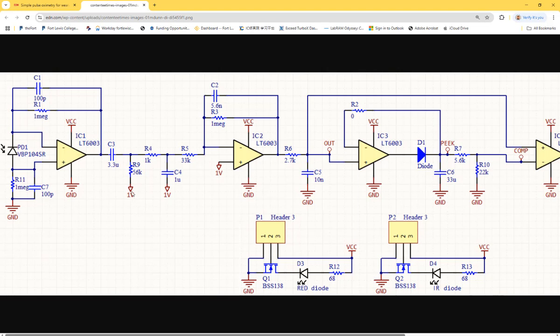But usually we use 50% of the VCC as the default DC offset. We always want your signal to swing around 50% of the range. Here's your top power rail, here's the ground, so it's basically half of VCC or VDD in the middle. So maybe 1 volt is 50%. If it's a 3-point-something VCC, then it's very close to 50%, which is good. Okay, I don't know yet, but it seems like it is.